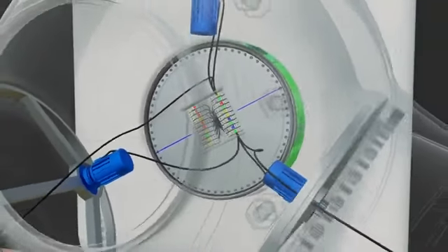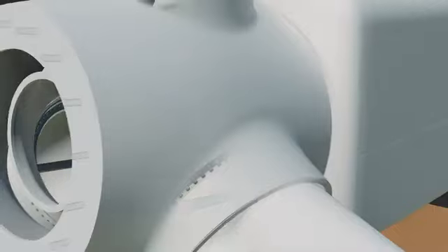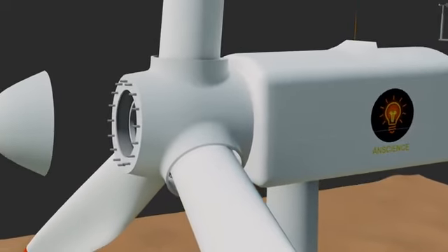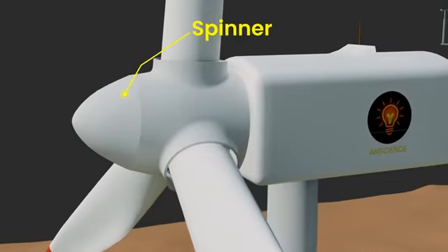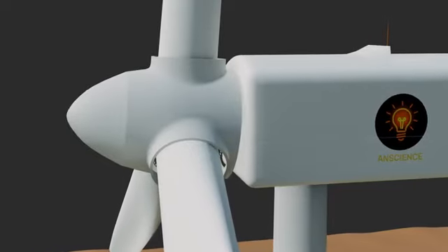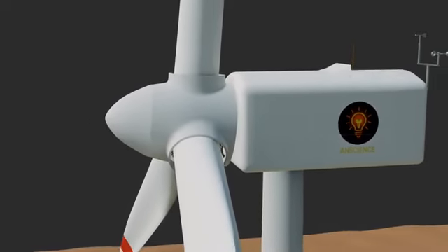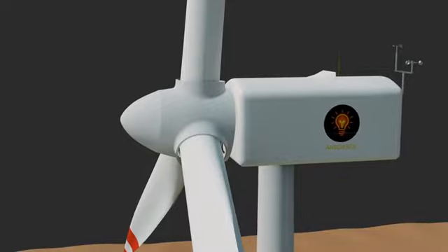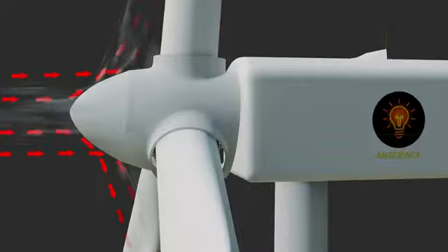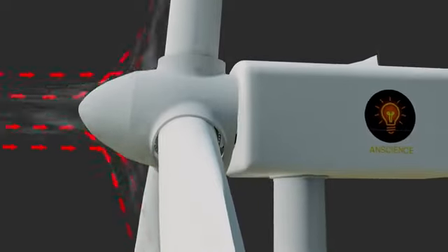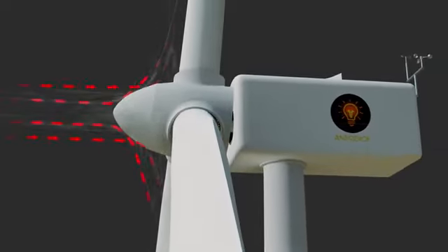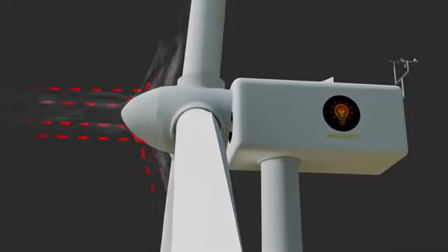The center of the rotor is a flat, blocky piece of metal. Wind would hit this flat surface and create drag. The nose cone, also called the spinner, is the aerodynamic cover attached to the front of the rotor hub. While it looks like a simple cap, it performs several critical functions for the turbine. It is typically made of lightweight fiberglass to resist corrosion and weather. The spinner's curved shape guides the wind smoothly outward toward the blades, improving the overall efficiency of the turbine. It acts as a weatherproof shield. Inside the spinner is the pitch system. The spinner keeps rain, snow, salty air, and lightning away from these expensive components.